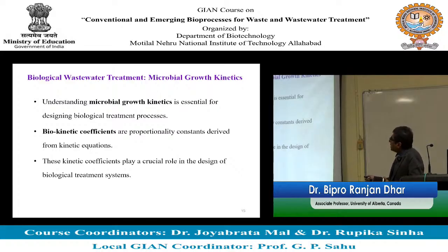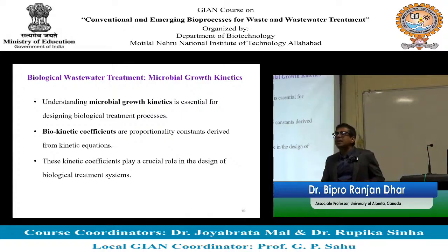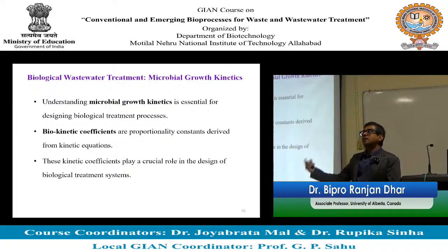So from microbial growth kinetics we can get different types of kinetic equations. And from those equations we can get different kinetic coefficients that represent the growth kinetics of the microbes you are using in your system, right? And those kinetic coefficients can finally be used to develop design equations.